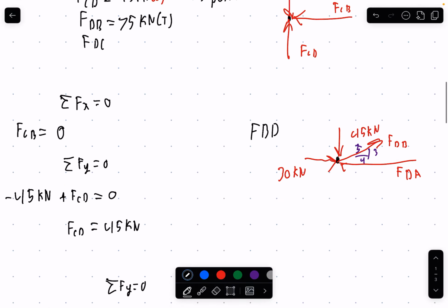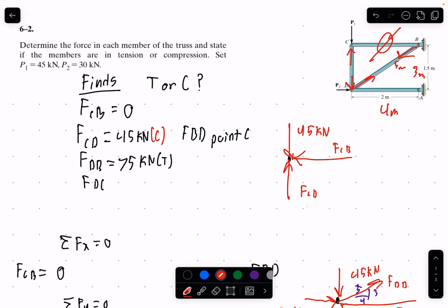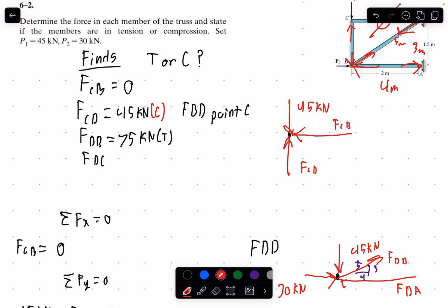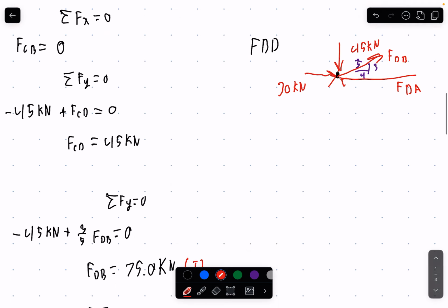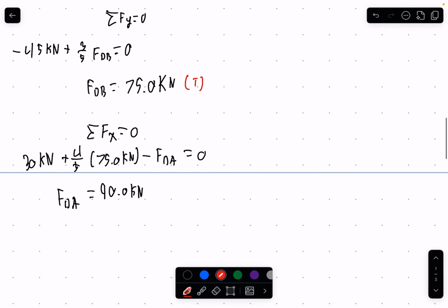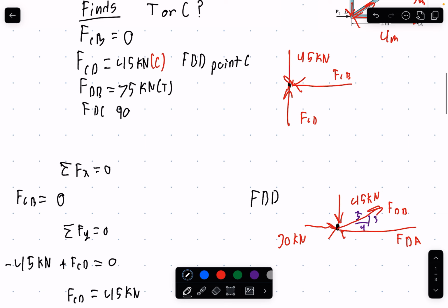So we know that we're correct with how we assumed the force to be initially. And again, if you take a look at it, this rod will be in compression because the force exerted on the 2 points is being opposite. So we know that this rod must be in compression. Okay, compression, and that'll be our last find variable: 90 kilonewtons, and that will be in compression.